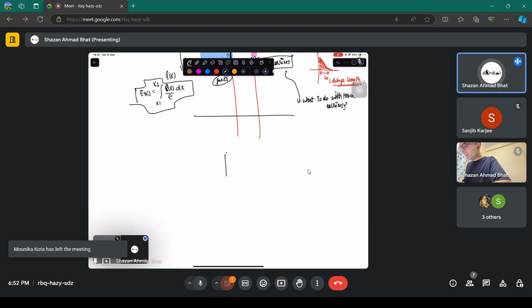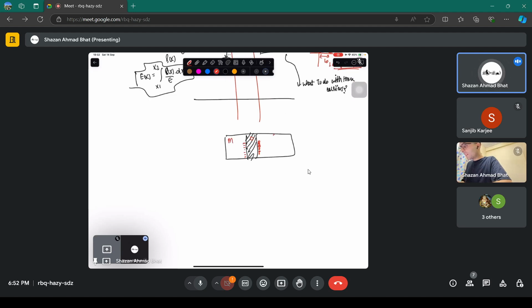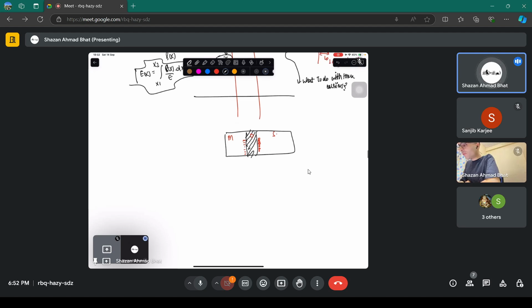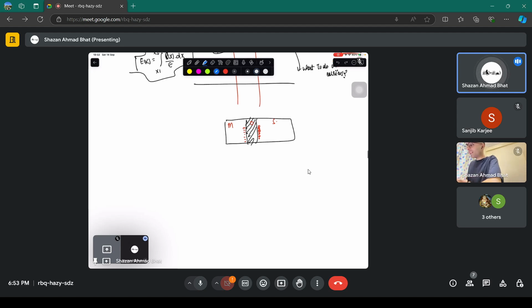It is like you have an oxide, and you have made so many carriers at this particular place, and there are electrons at this place. This is metal, this is oxide, this is semiconductor. Now what are you going to do with this? Anyway, the carriers are not going to move through the oxide, because oxide is a dielectric. It's not a conductor, it's an insulator. So this particular system is used to test how a particular device is going to